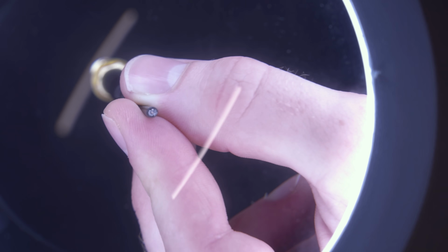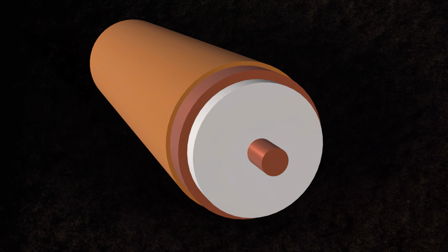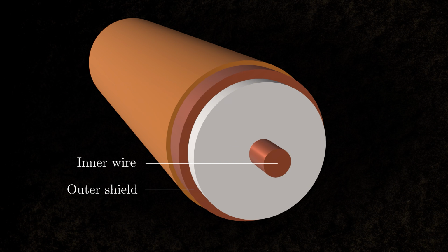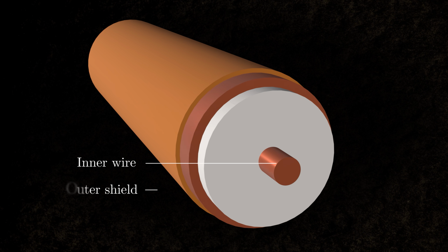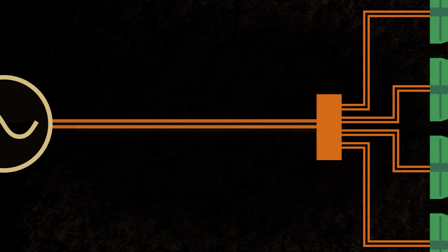So instead of adding an inductor or capacitor, we get the same effect by just using a length of transmission line. So we need to cancel out the imaginary part of negative 1.8. Now, the cable we're using is coaxial. It's really 2 conductors, an inner wire and an outer shield held a precise distance apart. Normally it just runs to the antenna, carrying the signal in a loop.